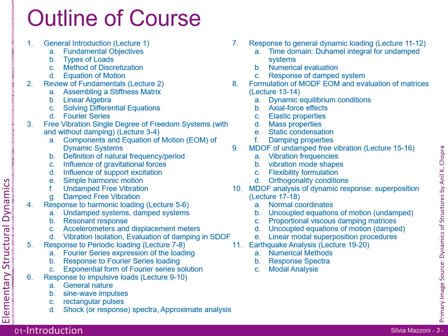But it's not a very difficult concept, and it's actually a beautiful concept. Then we're going to look at the response to impulse loads, such as a shock, a load that's applied over a very short time. Why is that? Because then we're going to use that to integrate over time and pretend that a random input is actually a sequence of shock loads. So it's kind of neat how we can do that in computing the response to these impulse loads and then to random functions. So we're going to look at learning what an impulse is.